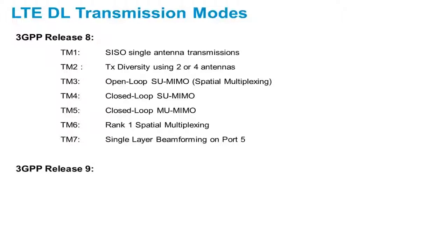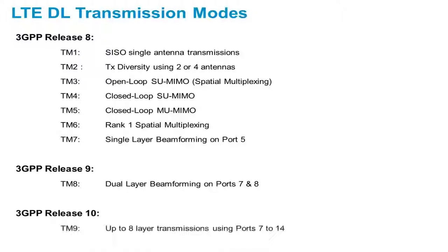Release 9 introduced transmission mode 8, supporting dual layer beamforming on port 7 and 8. And finally, Release 10 introduced transmission mode 9, supporting up to 8 layer transmissions.